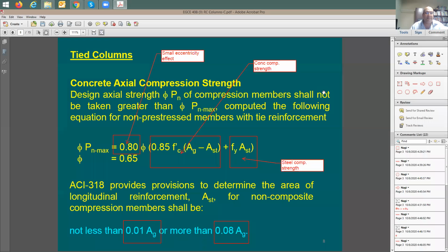Say that you have an equation. This equation for the axial column capacity. So phi Pn is going to be the axial capacity. Is equal to 0.8. We said this 0.8 is a reduction factor to account for some small eccentricity. So this axial component here, or this axial strength, considers that you're going to have some small eccentricity and you can ignore it. Ignore what? Ignore the eccentricity. So generally speaking, eccentricity is going to be causing additional moment that goes with the axial column load.